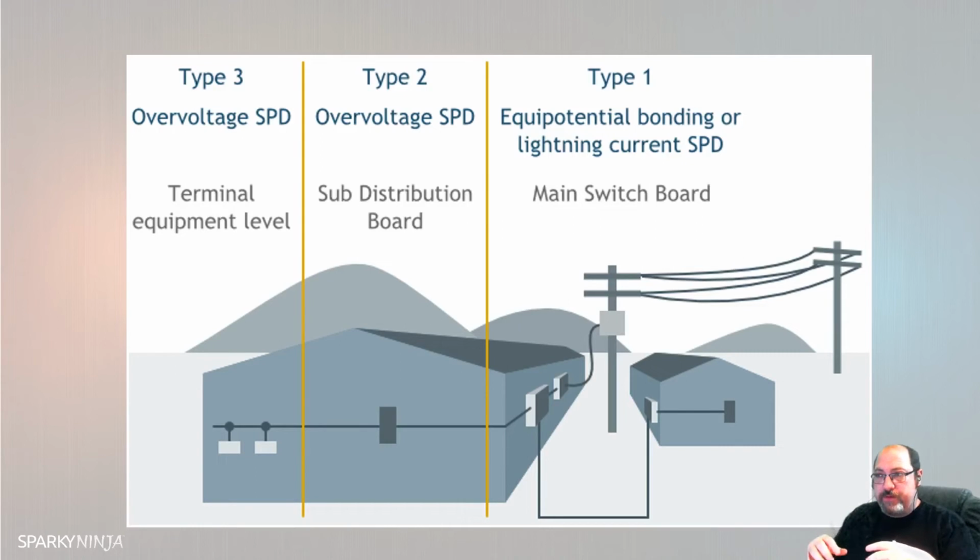So quite often the risk here is when we have these voltages coming in from a lightning strike, they're looking to come back in. They come in, they go down, but they try to come back into our system through our earthing. And so what we need to do is decide where the boundary is, where the biggest risk is, and what type of SPD we put there?